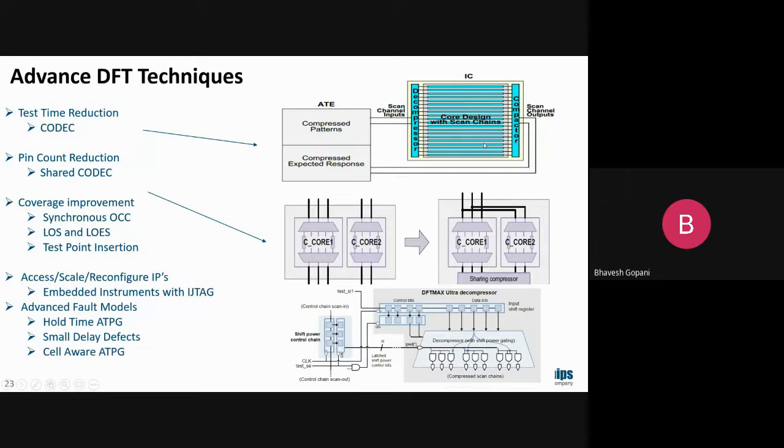Another thing is power, in the sense of shift power and capture power. Power is a very important parameter. The third one is IR drop. These parameters need to be taken care of at the initial stage of the insertion as well. So this architecture and these techniques are defined before starting the insertion, and then accordingly we need to work.